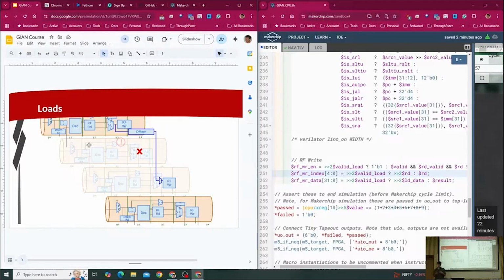You might have to change opcode values or the entire instruction depending where you figured that out. It's much less impact physically to the logic if you are careful about the control logic and use things like valid signals. So yes, we factor valid into isLoad so that we only have this impact for valid instructions, valid loads.